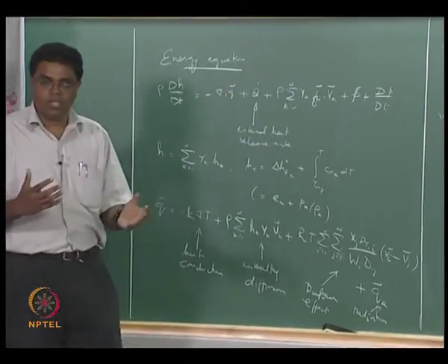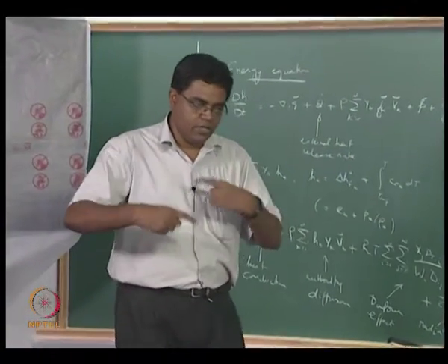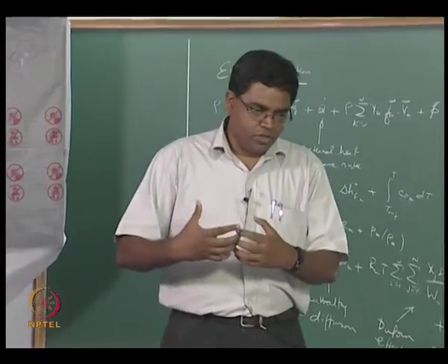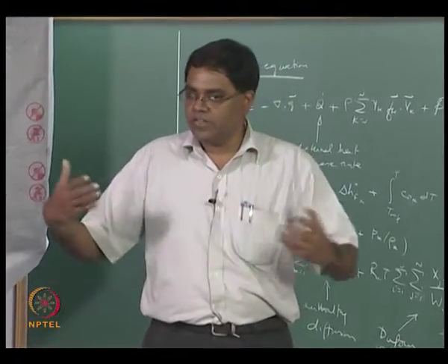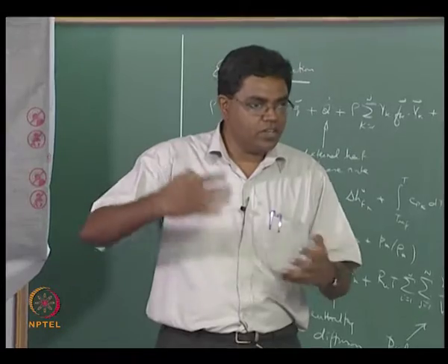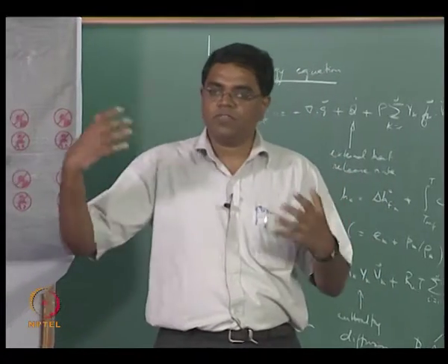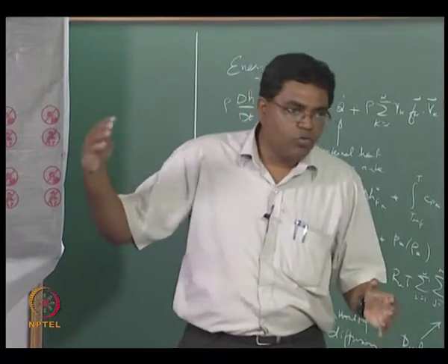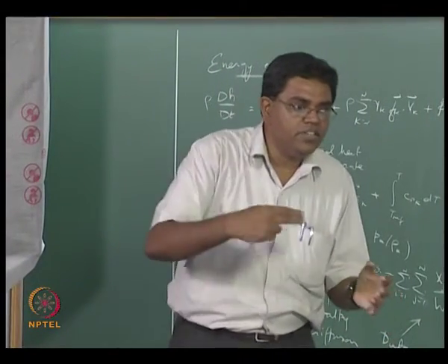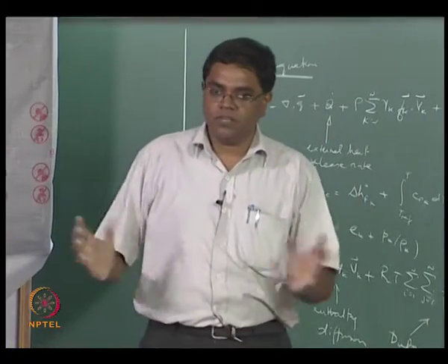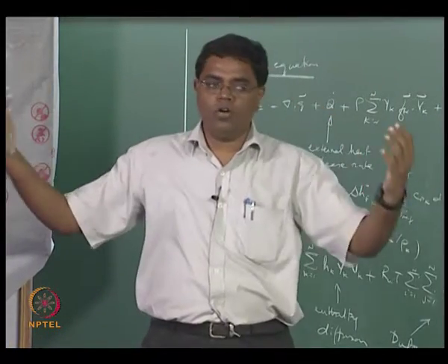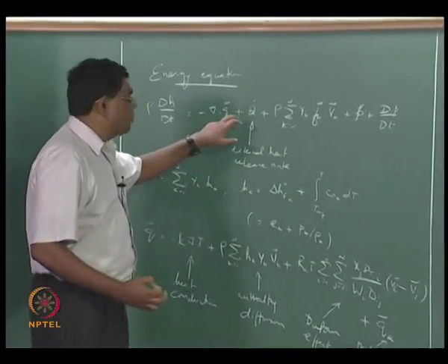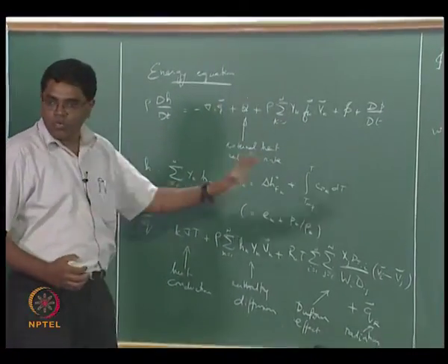So this is typically coming from things like if you now have a very complicated geometry of something like electrical wire, or let's say nuclear rods or something of that sort that is giving rise to heat that is outside of the fluid, but you want to now keep that within your domain because it is too complicated for you to negotiate the fluid within these parts, but you want to just kind of say on a spatial distribution basis the per unit volume heat release rate would be so and so, if you want to just plug that in.